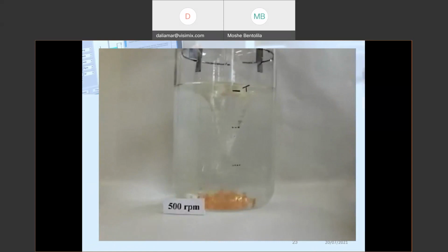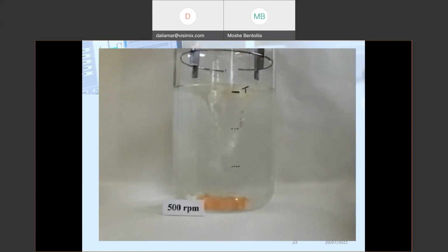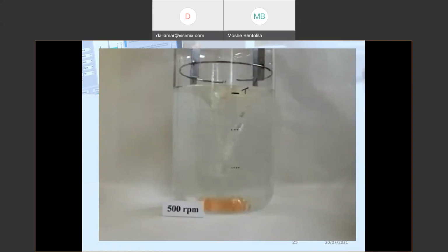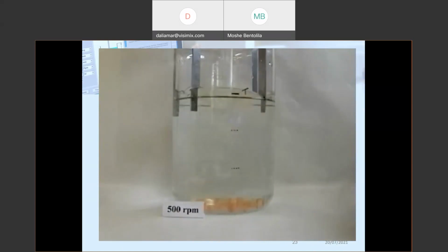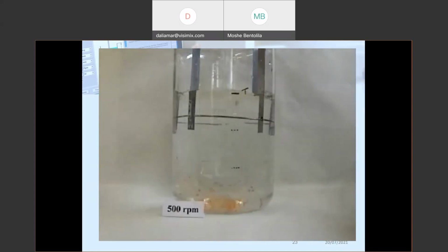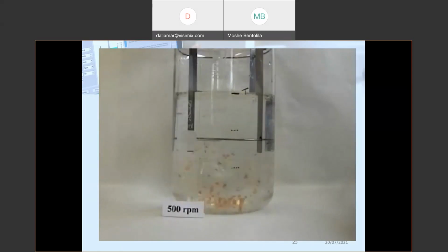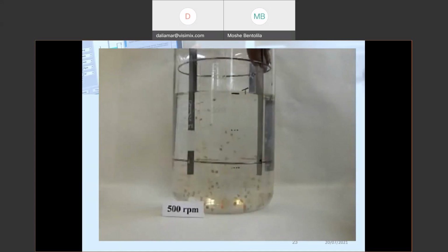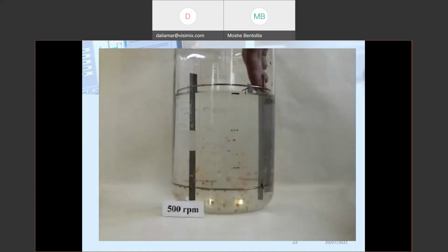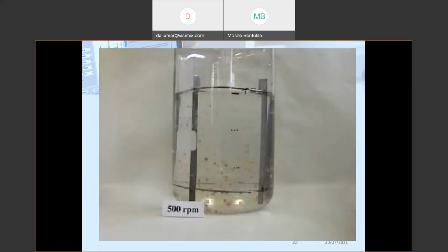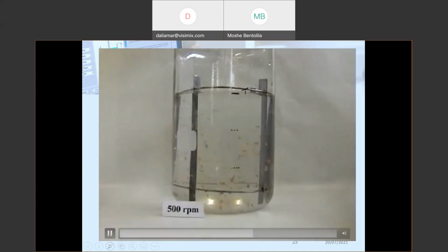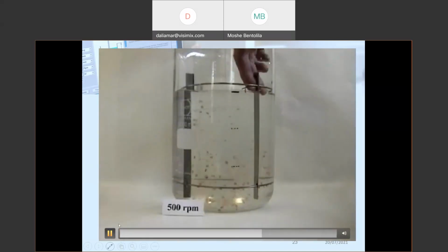In this case we are feeding a baffle, but it's like having another piece of equipment in another place. You see how different the mixing can be, how different the mass exchange can be, and we need to calculate it. One time like this, second time like this, and the RPM is only a tool to change the condition. But what is really controlling my process is this one: the solids at the bottom, the vortex disappearing or happening in some partial way, and it happens in every equipment. So take care of it. It's our job. Only you will be able to do it, no other people in the company.